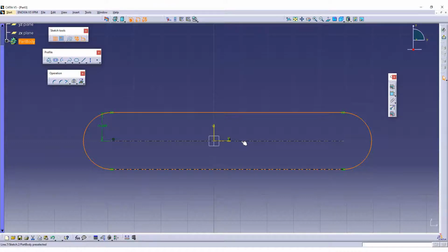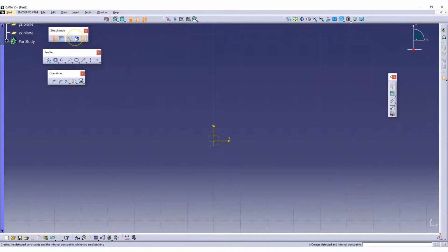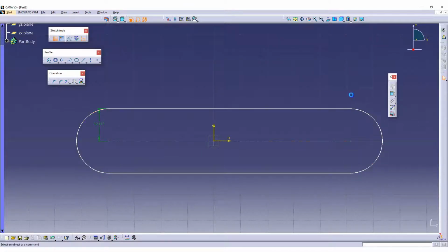Yeah, thank you. So now, the moment I make this on, you can see it's on. If it is off, this constraint also will not come. The moment I make this off, what will be the geometry? Sorry, I'm going to draw once again and make this one. See that your geometrical constraints will not appear. Your dimensional constraint is appearing, but your geometrical constraint will not appear. So that's a very, very important fundamental thing. So you have to give all these constraints.